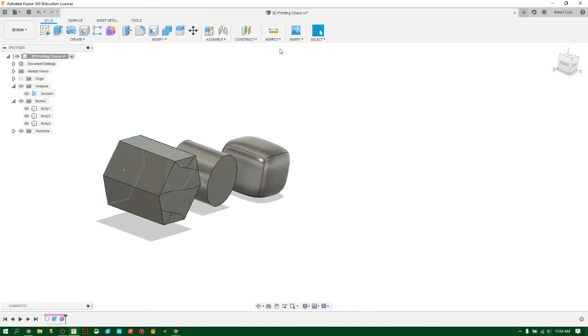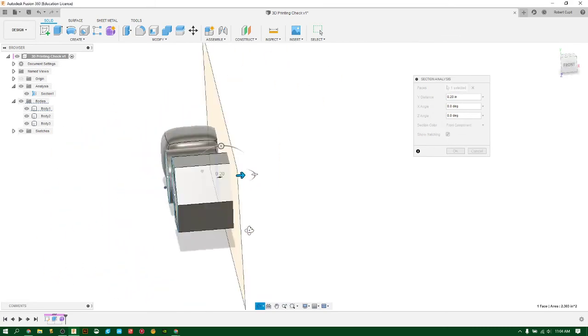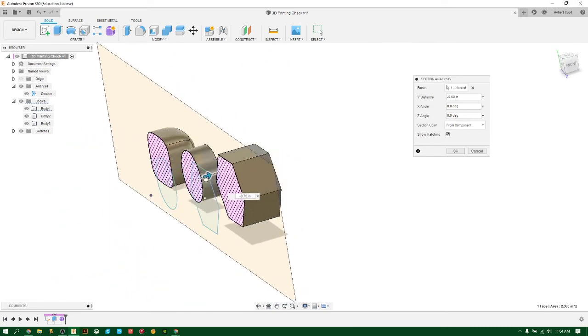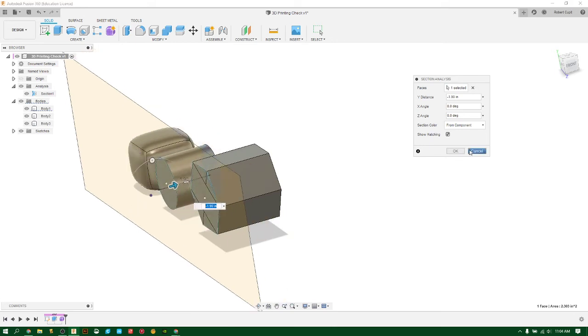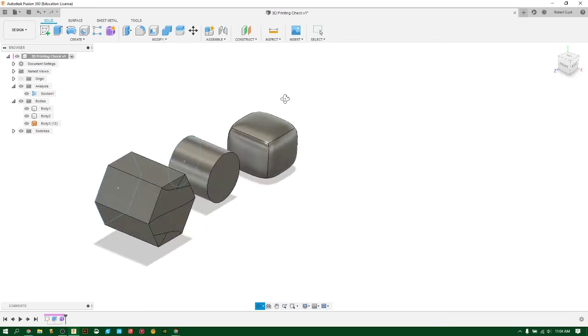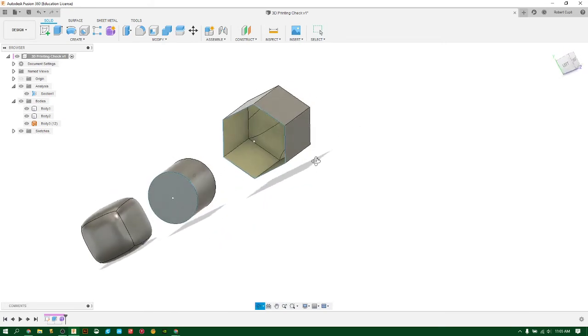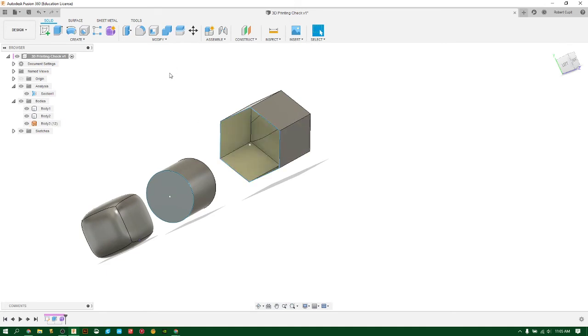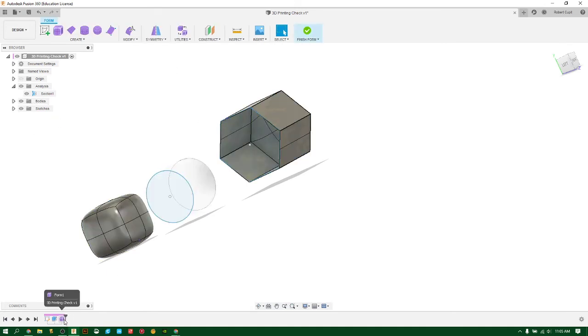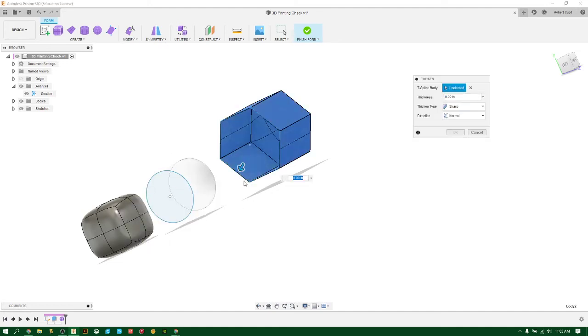Again, if I finish form, inspect, and see section analysis though, I do not still have, oh in this case I do, look at that, I got lucky. Sometimes it still won't be a solid piece, okay? If both of those are solid, like you said, I just took the other piece away, and I got one side that is, you can see it's still hollow. You can either close off both ends and it'll make it solid, or you can go back into that form, and you can go to Modify and Thicken, and I showed you this a couple times, and go negatively inside, press OK.